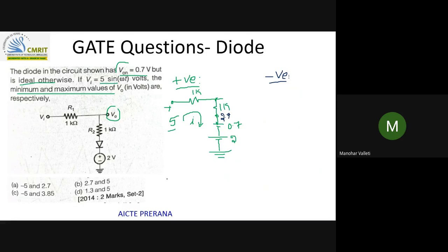So I will be (5 minus 2.7) divided by 2k, right? Here 5 is there, this resistance, and this is open, right? So current won't flow there. This is open, here V0 is there. Current won't flow there. So whichever I is coming, it will enter here. So (5 minus 2.7) by 2k.